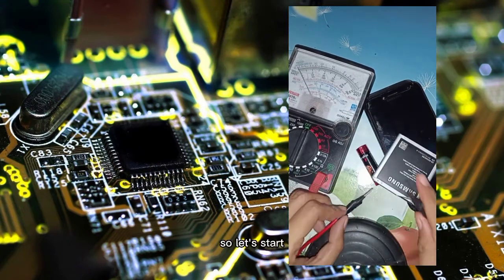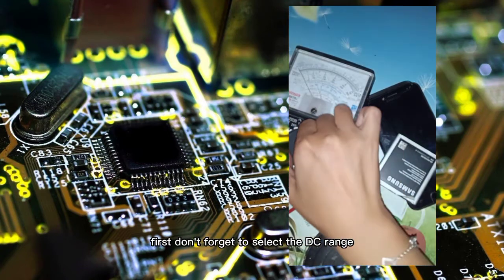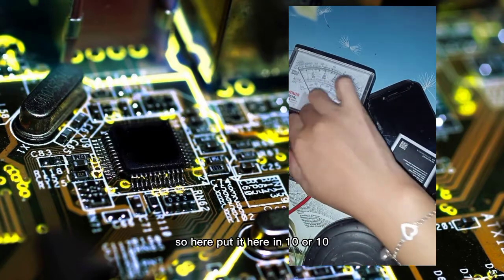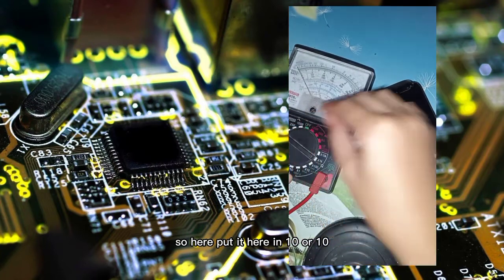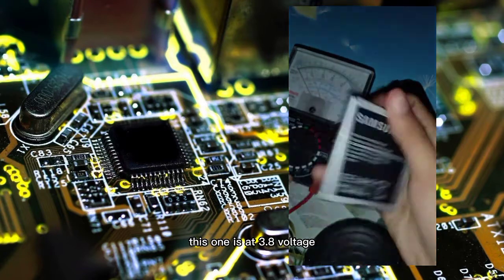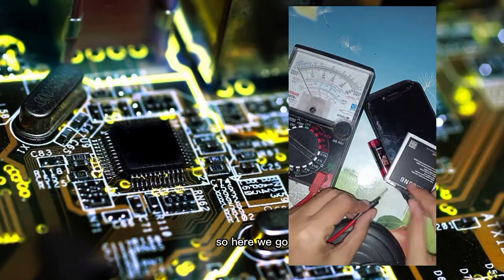So let's start. First, don't forget to select the DC range. So here, put it here in 10. This one is a 3.8 volt battery. So here we go.